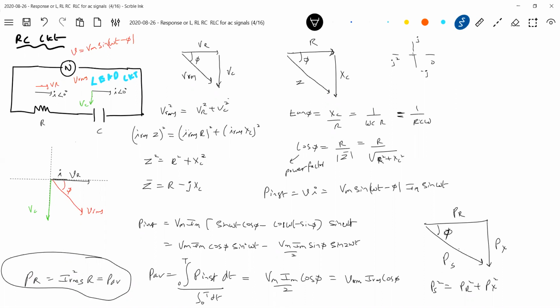Again, what is the wattless current? IRMS sin phi here also. A component of current is responsible for power. The other component is not responsible for power dissipation. There are some applications where IRMS sin phi is useful. Of course, we don't study that, but in designing of equipment, that is also very important.